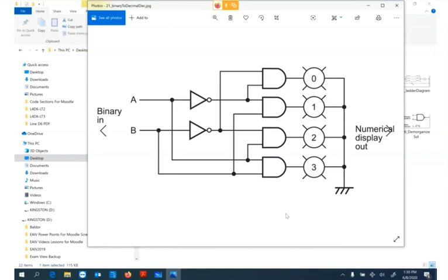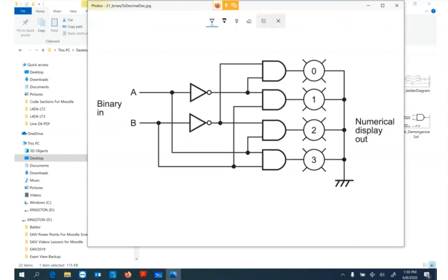Here is another one. Now, hopefully your module is updated. I think there's an error in my book, but just looking at these numbers here, 0 through 3, this should be your least significant digit right here. So 0 would be your least significant. So right now with zeros here, and this is a neat little exercise to try, that means there's a 0 here. And that's an inverter gate, so that means you have a 1 on the output.